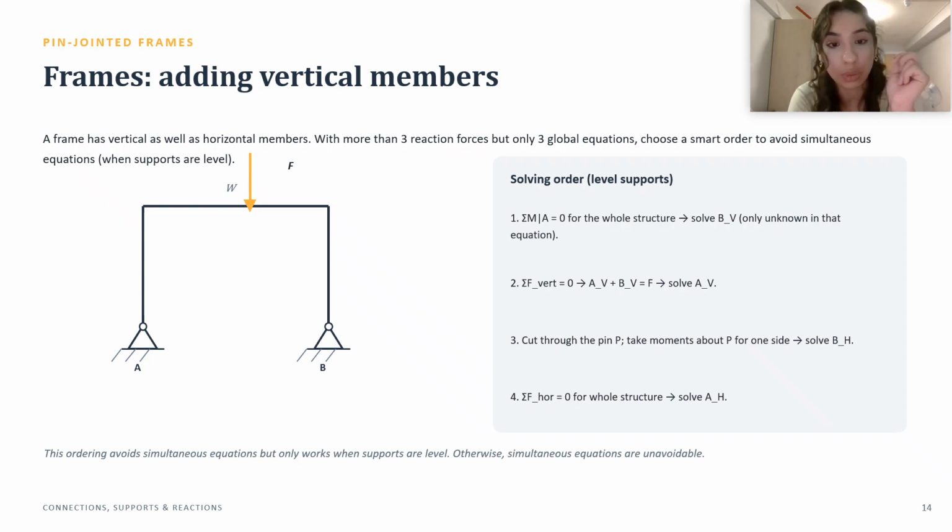Now there is a thing though, which is very cool. The force BH, the line of action of it, goes through A. So that also disappears. We end up with only BV, okay? And usually we get all the distances we need.